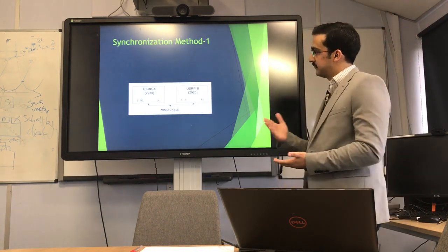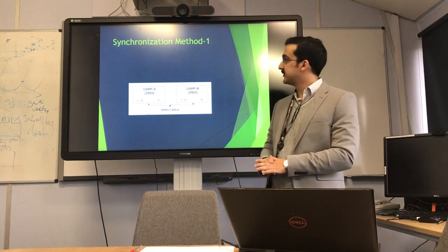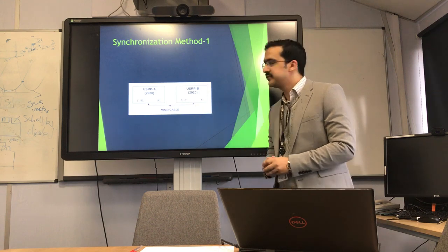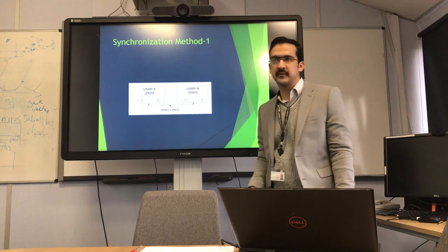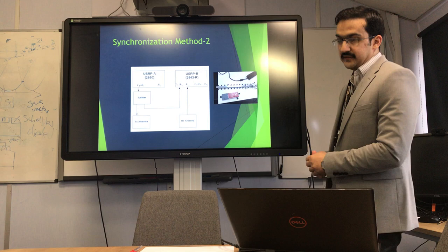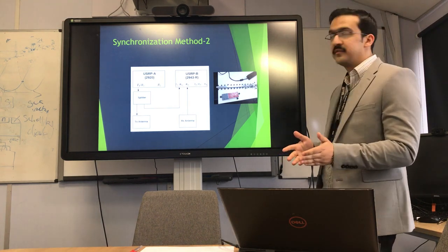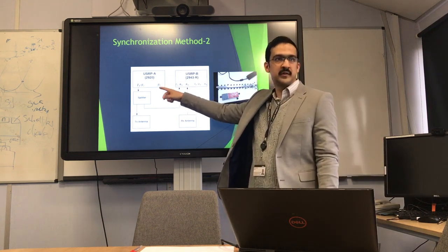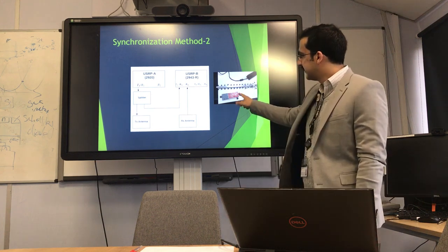As you just saw, bistatic is the right solution. So how do we synchronize the two USRPs? If I'm using USRP 2920, a MIMO cable comes with it. You just connect the MIMO cable and the two devices get synchronized. Now at UCL I had a USRP 2943 and a USRP 2920. How to synchronize these two? For that we use a splitter.